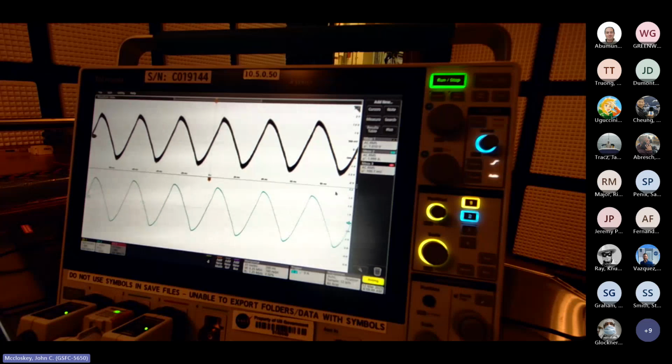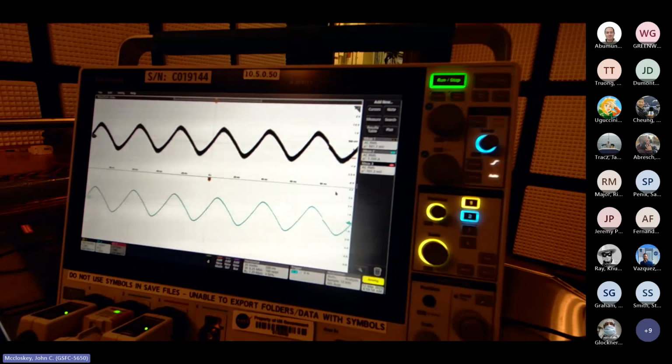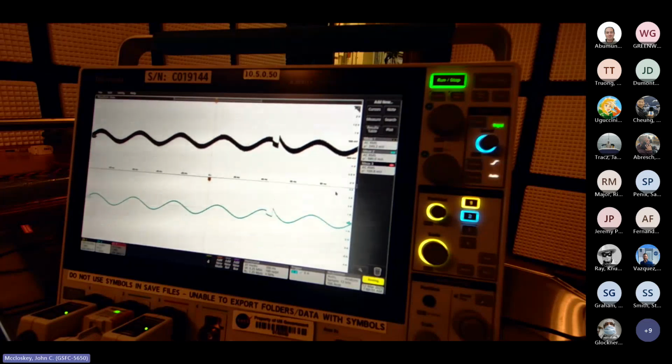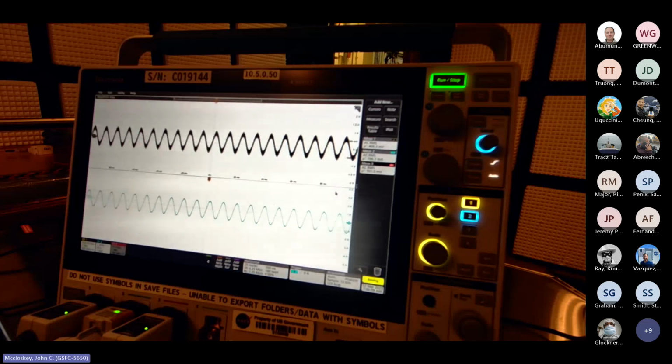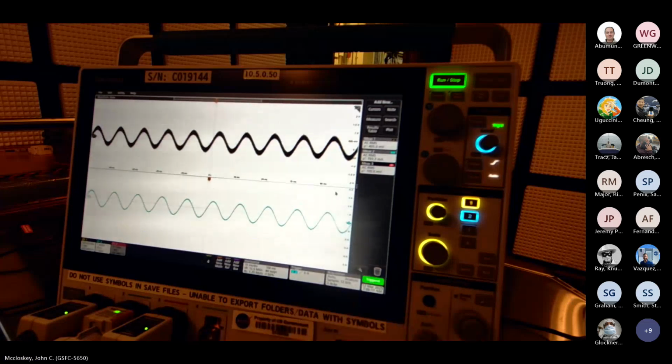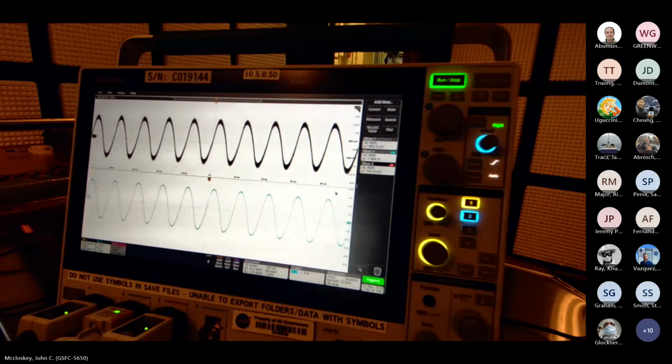So anyway, I'm going to go to the amplitude. It's a pretty good jump from 30 to 100 hertz. I'm going to drop it by about 10 dB. And so now we'll go up to 100 hertz. Okay. Now we can bring it up to level until we're seeing our desired 1 volt. Change the frequency scale. Okay. There we go.